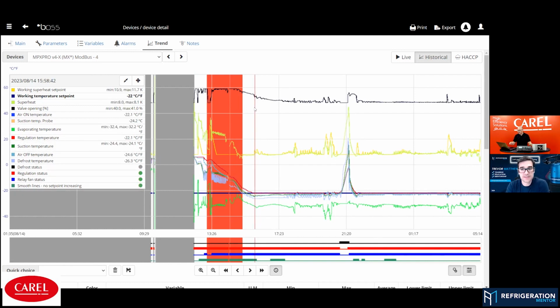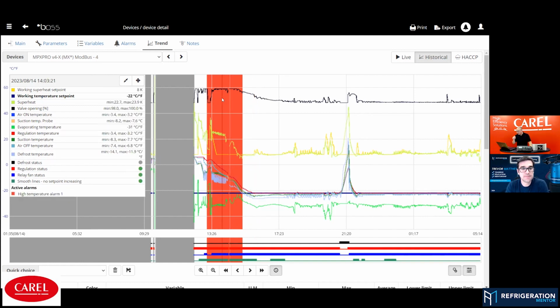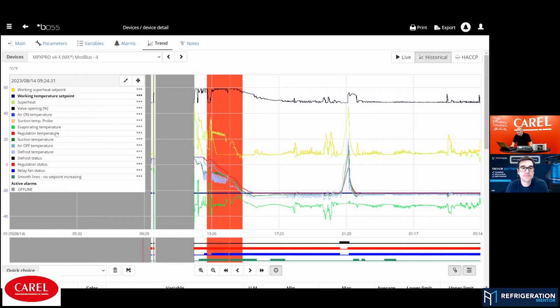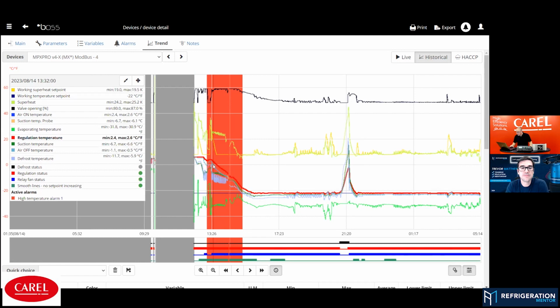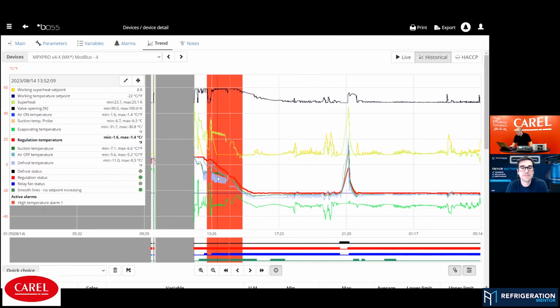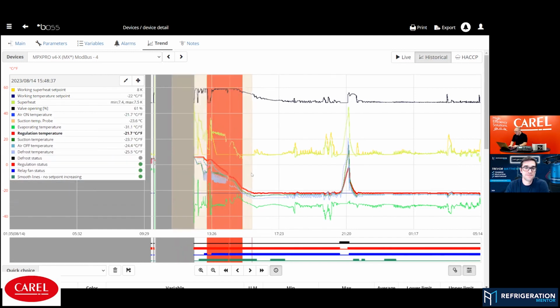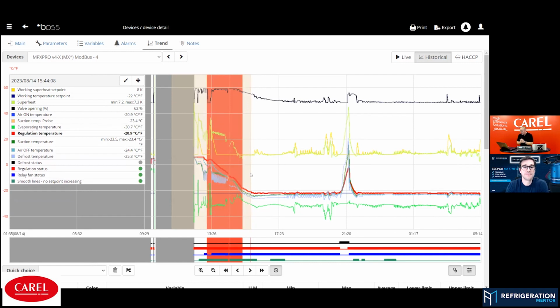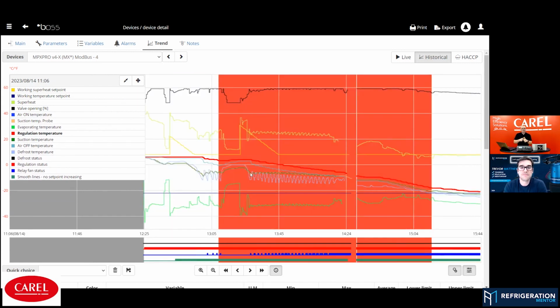energetic optimization. Yeah, but the problem here was really, why is this cold room not reaching its temperature, and why is the regulation temperature behaving so strangely? We were checking everything remotely. Let's make it a bit bigger. The first idea was, not enough refrigerant. Okay, we can cut this topic out. We have checked this. Our application has enough refrigerant.